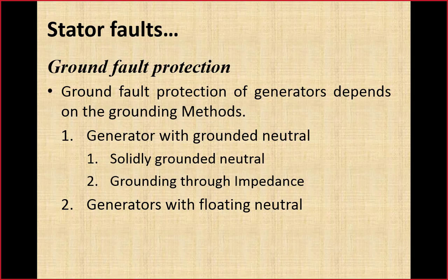Second grounding method is generator with floating neutral. The behavior of generator in this condition, and if we had connected neutral through ground fault neutralizer, will be the same, because ground fault neutralizer, that tuning coil, makes the system virtually ungrounded. Meaning behavior of system will be similar to an ungrounded system. So we can categorize that condition into this floating neutral condition.